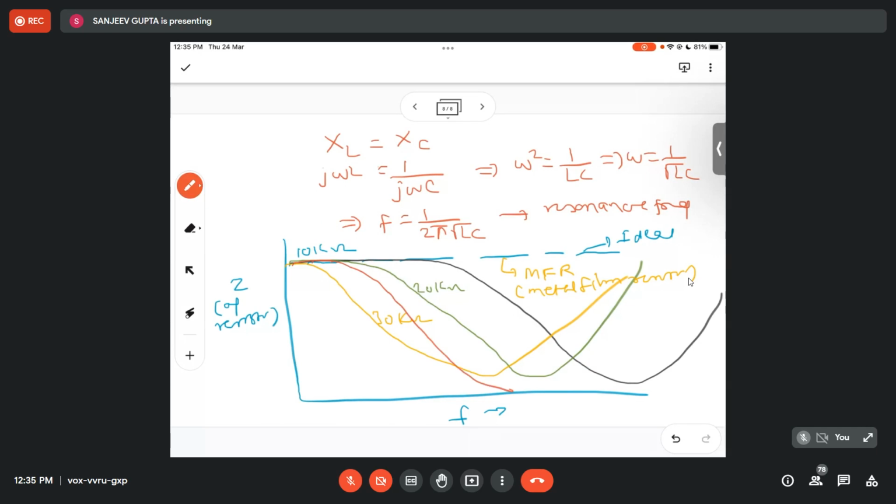So this is the behavior of a carbon composite resistor. That means inside the carbon is there. So it has a higher power handling capability, about half watt or so, as compared to the quarter watt power handling capability of a metal film resistor. So this is for the carbon composite resistor of the same value, 10 kilo ohm. The 10 kilo ohm metal film resistor has a slower decay, but the carbon composite has a faster decay.